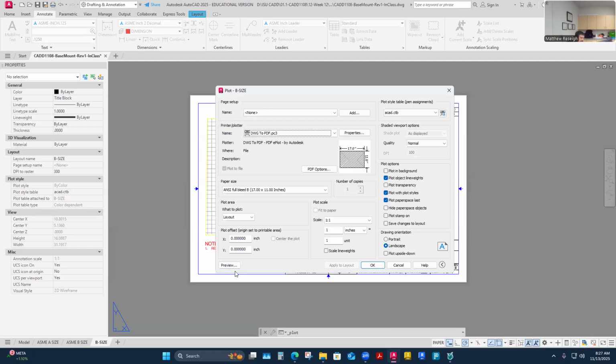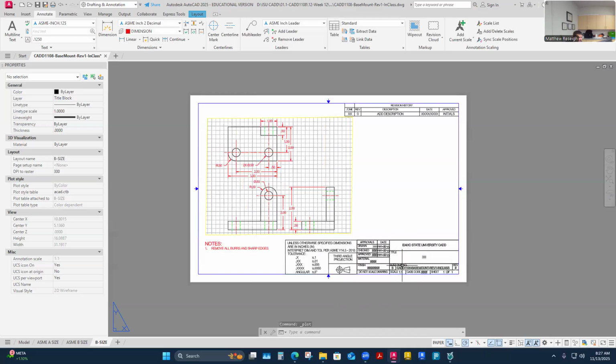I'm going to guarantee you probably have. It's this dialog box that says something about a batch plot, something about a single sheet. And all we've been using so far for our PDFs is single sheets, but I'm going to say, if I had this drawing done, how would I do all these sheets as one PDF? Well, if you've already selected this, it's just going to want to make a single sheet from what the layout is on. So I'm going to just cancel this real quick.